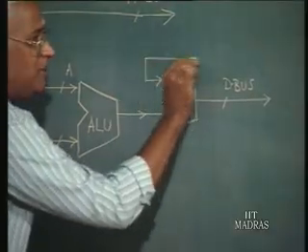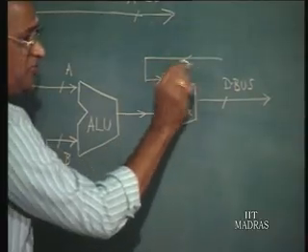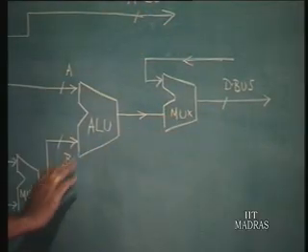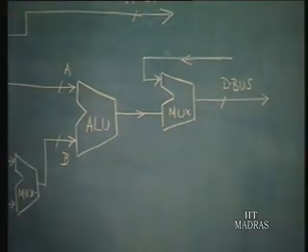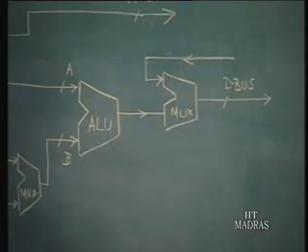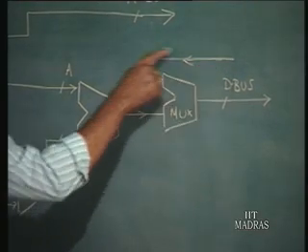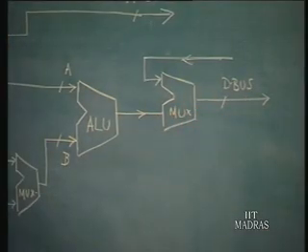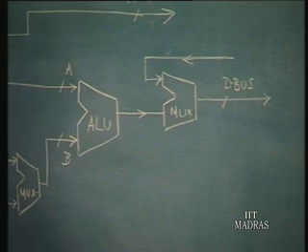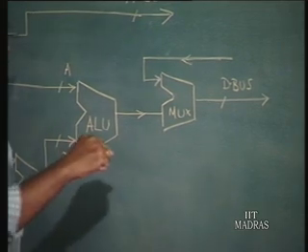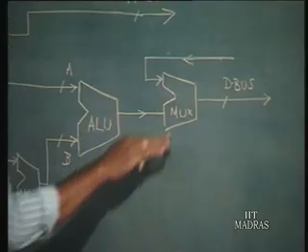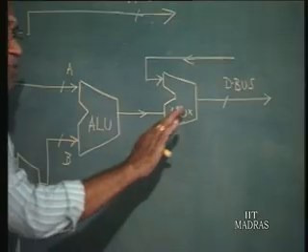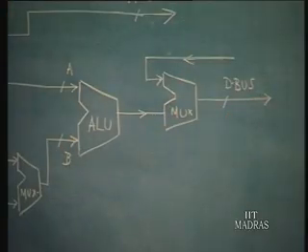input part of the data bus, that is, the data may come in. So, this is also in fact part of the D bus. You can see that sometimes the CPU will place data on the bus, and sometimes the data will be accepted by the CPU. When accepted by the CPU, the data will be coming over this. When the CPU places the data, it will be going over that, right. So, for instance, in the case of memory read, the CPU reads from the memory. The memory will place data on this and the CPU will accept it and route it internally. When the CPU writes into the memory, the CPU will send the data over this. So, that is the arrangement there.